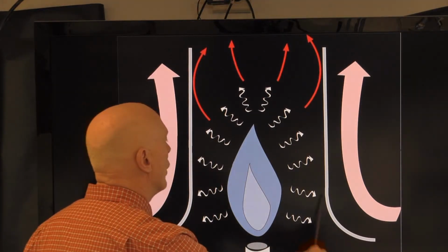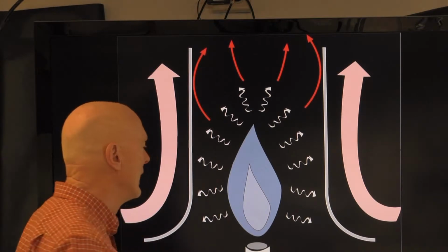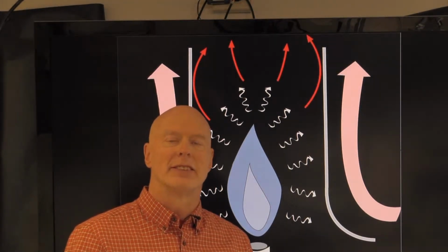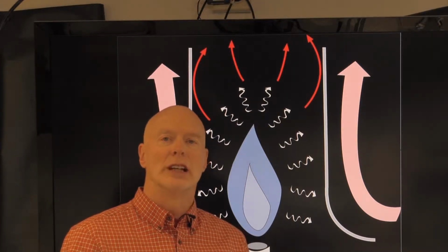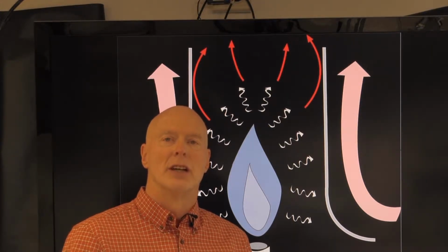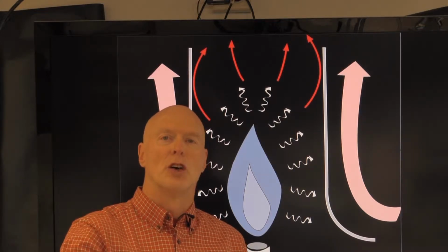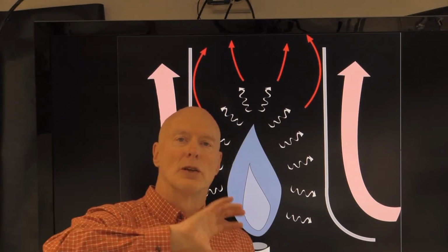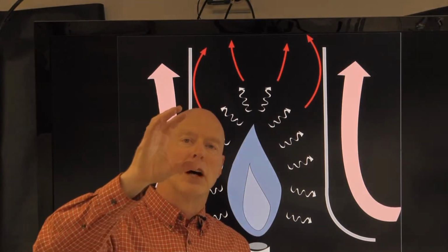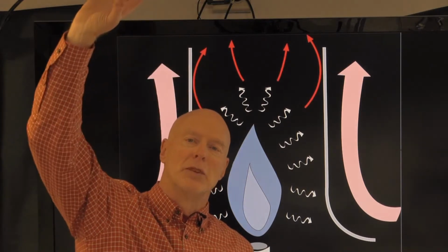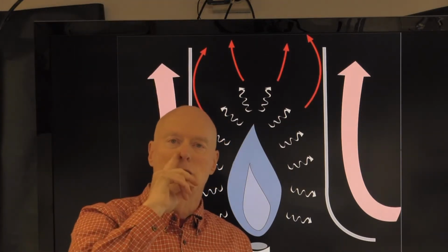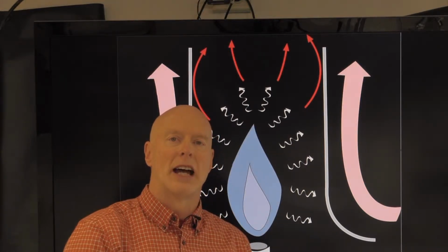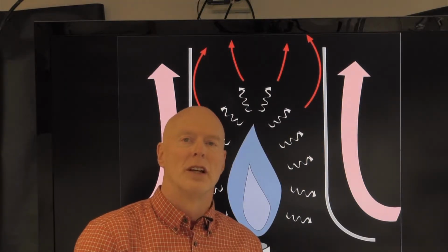What the metal enclosure is doing is keeping the combustion gases contained, and leading them to the flue, which goes out of the combustion appliance, so that the products of combustion go up the chimney and we're not exposed to them. We don't want to be exposed to these combustion gases because they're not healthy for us. That's one of the reasons.